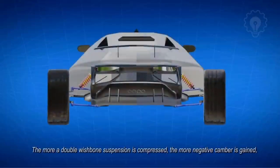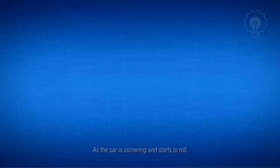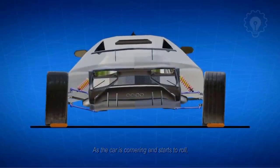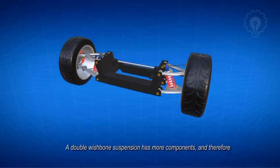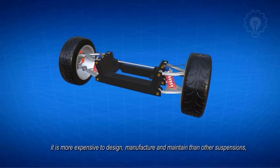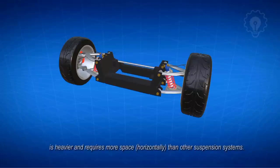The more a double wishbone suspension is compressed, the more negative camber is gained, due to the use of unequal length control arms. As the car is cornering and starts to roll, a double wishbone suspension system ensures better contact of the tires with the road. A double wishbone suspension has more components, and therefore it is more expensive to design, manufacture, and maintain than other suspensions. In addition, due to the large number of parts, it is heavier, and requires more space than other suspension systems.